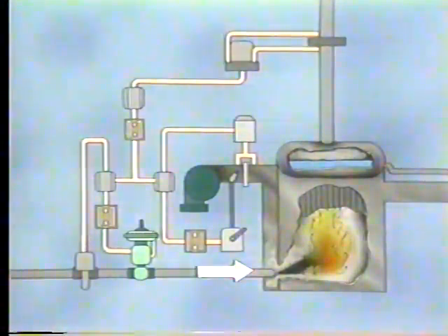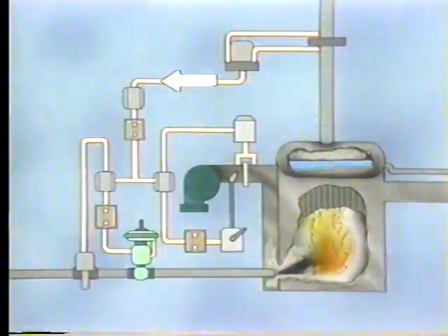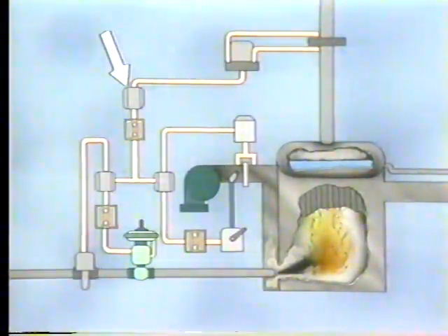To apply these general principles of cascade control to the boiler system we've introduced, let's refer once again to the illustration of the boiler. Here's the boiler with the instruments that make up the cascade control system. In this cascade system, the rate of steam flow is used to maintain the proper rate of fuel flow and airflow in the furnace. This transmitter measures the rate of steam flow from the boiler, produces a signal that represents that value, and sends it to this controller.